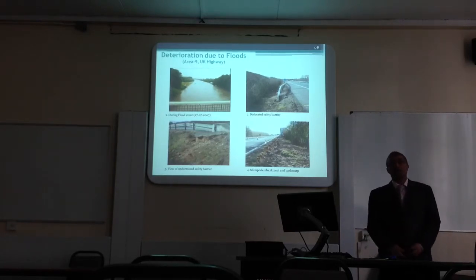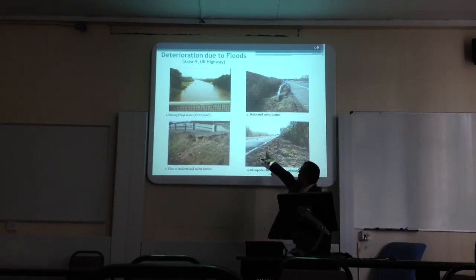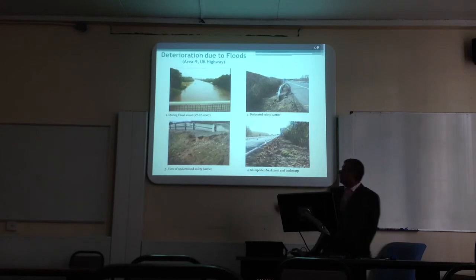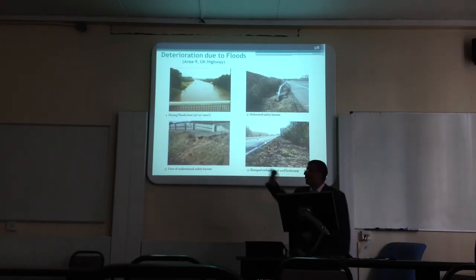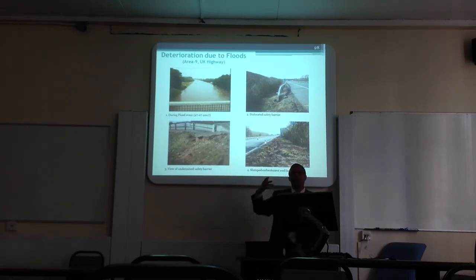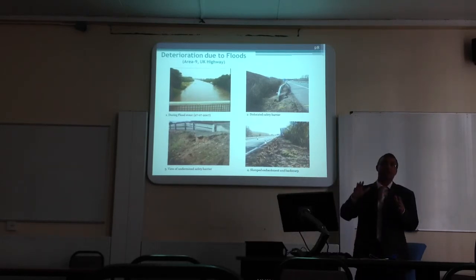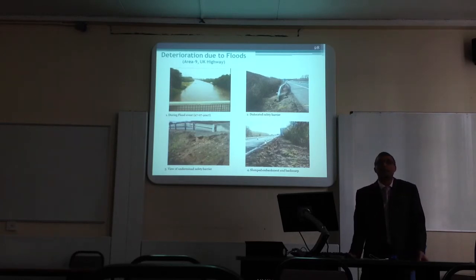undermine the embankment, and the embankment actually collapses during the flood water rather than post-flood water. There are other cases, that's all. That's why, if you can see here, the erosion will occur here, which is very obvious. But the failure would occur to a large extent if there is a rapid drawdown. What I'm drawing to is, rapid drawdown's fine, but there are other deterioration situations.